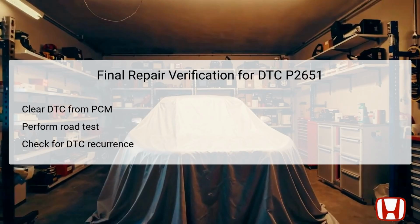After completing all necessary repairs, the final step is to verify that the issues have been resolved. Start by clearing the diagnostic trouble code from the powertrain control module, PCM, using the HDS. This step resets the system and allows you to monitor the engine's performance without previous faults impacting the readings.